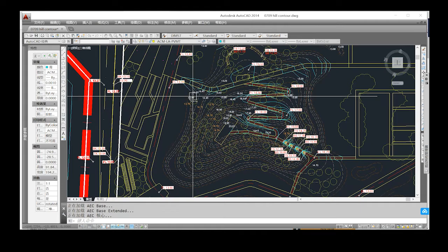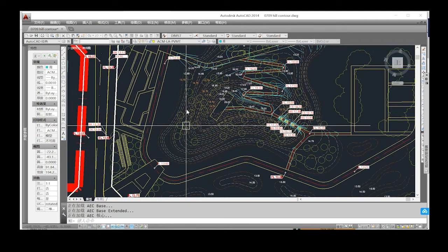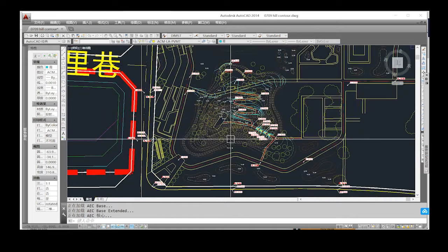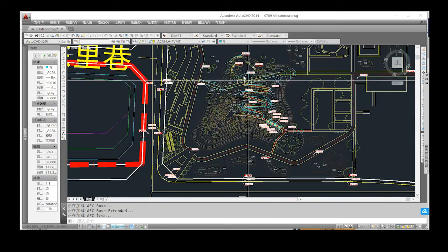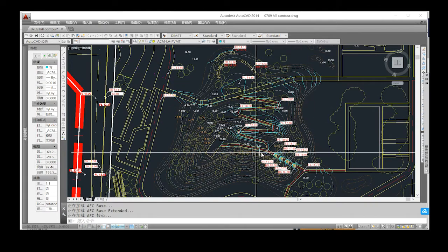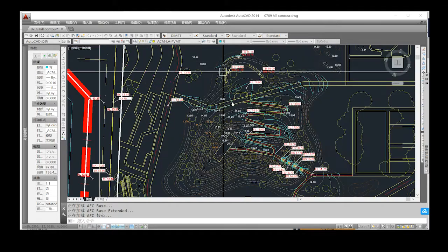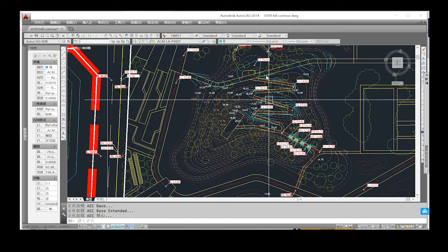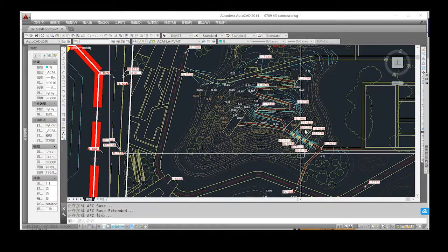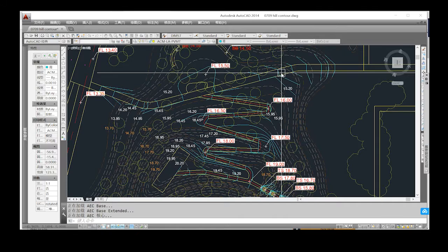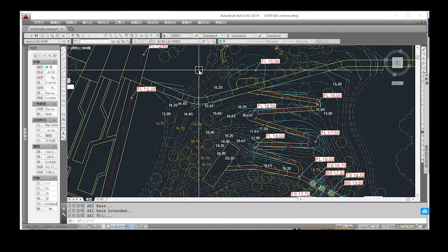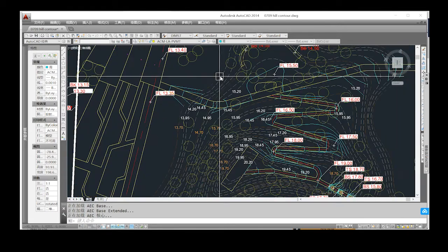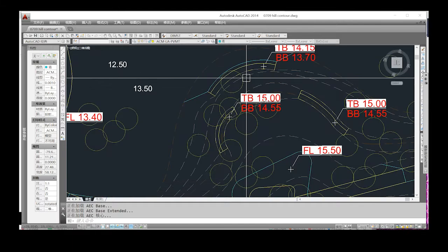And the second point is that contours don't overlay, but there are still some exceptions if you have a very tall structure like retaining walls or very deep dents, but in those cases the soils are retained too, so the contours can actually overlay along the retaining structure. But in this case, our modeling method just doesn't go along with the overlay contours.